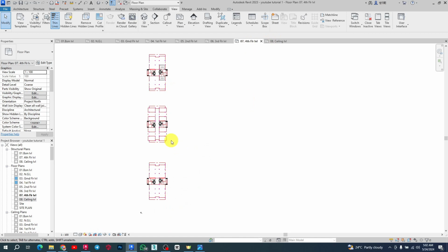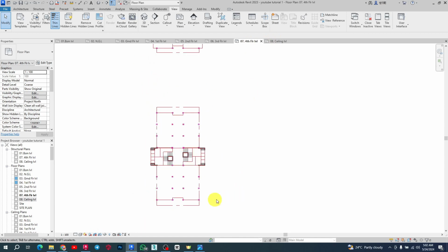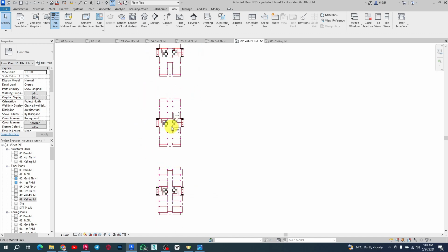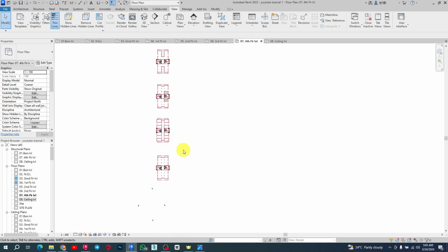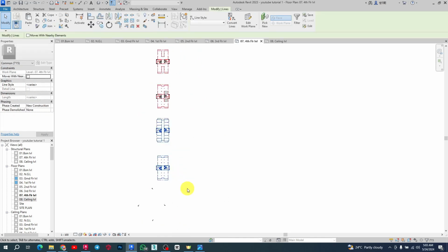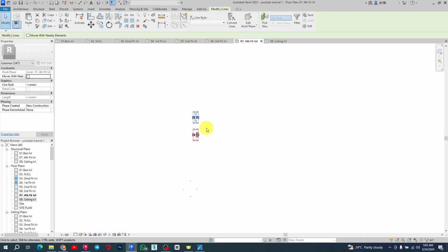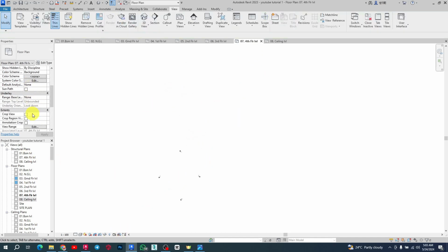Let's go to the fourth floor and see. So this is it at this level. So I think the third floor is the same as this. Okay, this is the third floor here. So I'm going to copy this. I'm going to delete these two at this level. So this one, copy at the fourth floor where we have to have the swimming pool instead. So I'm going to copy this level down to the fourth one. So I'm bringing it here. Let me underlay probably the second floor. I'm going here to underlay probably even the basement. I don't have any issue with that.